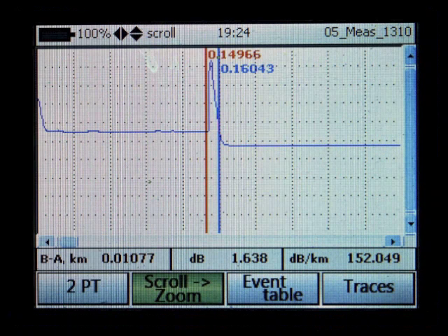When we reset the parameters, we went to a 6 nanosecond wide pulse, the narrowest available to us. That maximizes the resolution of the OTDR, which is important when measuring short cables. And it also reduces the amount of energy in the pulse, which is reducing the ghosting that we saw in the original trace. This is why, when you know the cable plant you're testing, you can go in and choose parameters in the setup that are optimum for that cable.